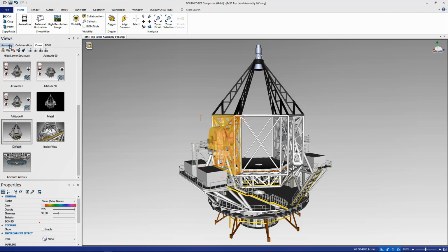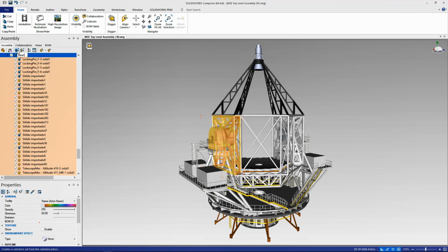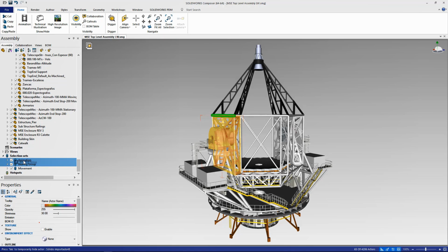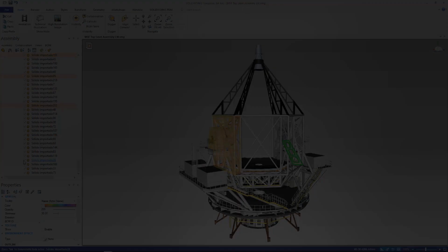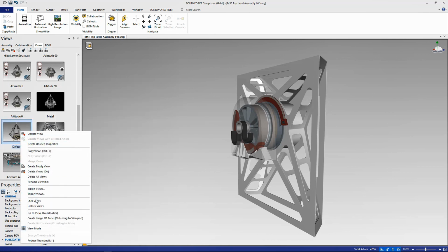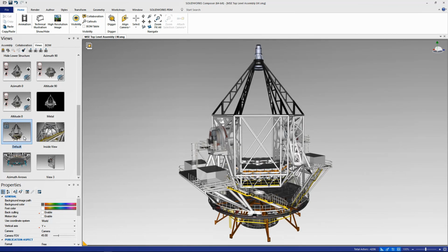To recall a previous selection, we can use selection sets, but digging through too many selection sets can be costly. With 2019, however, we can further organise selection sets and hotspots by creating groups. Views can now be locked to prevent them from changing accidentally. When this is done, an icon is shown on the thumbnail. Also, the indicator for custom views is now an icon in the bottom right hand corner.